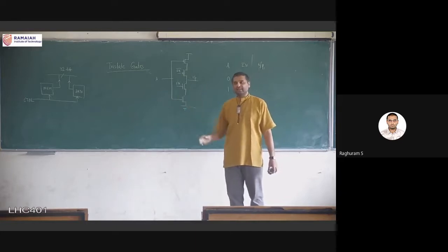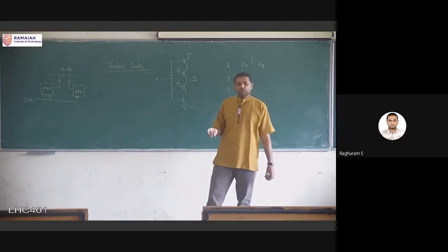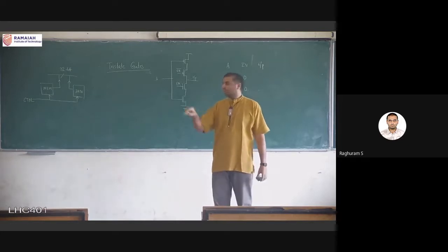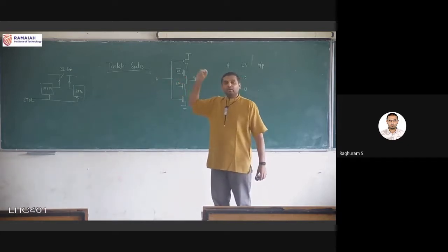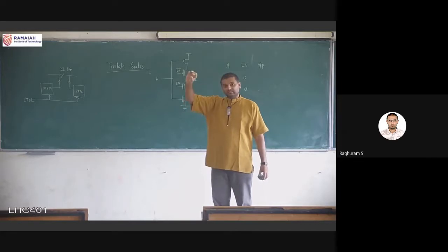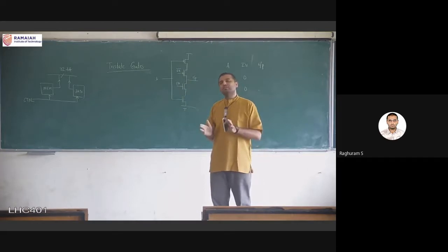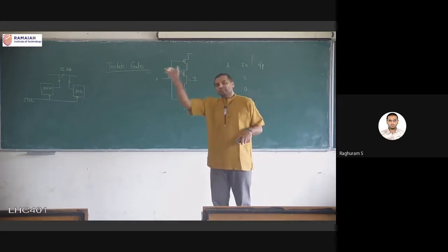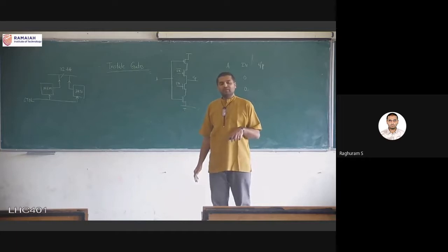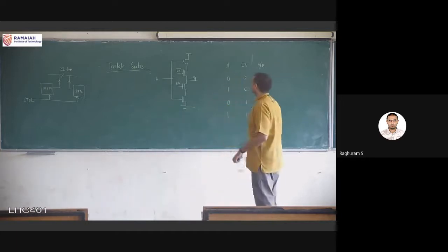Z. Z is in some ways not a good value if that is the only value. Like we said in this example, I'm not allowed to put Z on any gate. That is, a signal cannot have a value Z, but the output of a gate can have value Z, which just means that it is disconnected. Some other gate is responsible for driving the signal. So that is what we will see here.